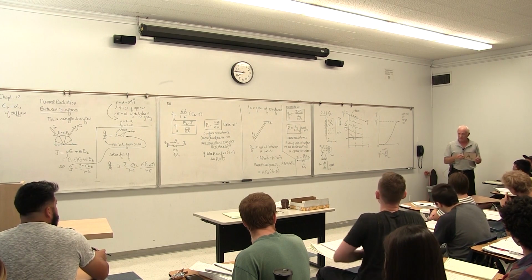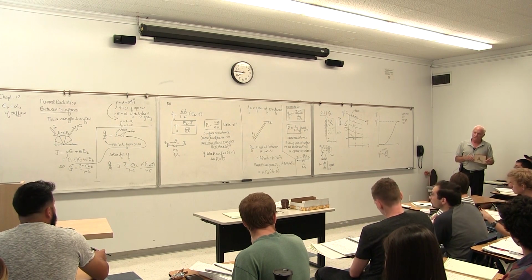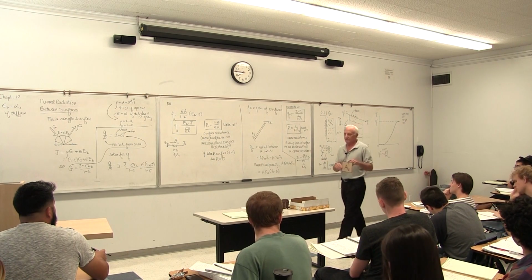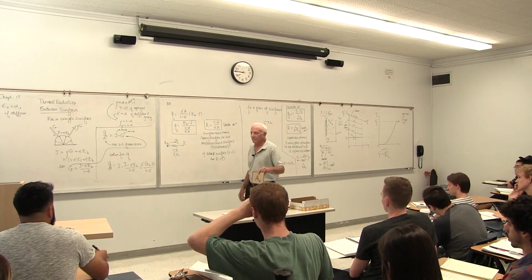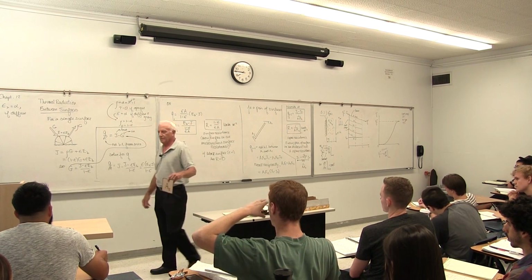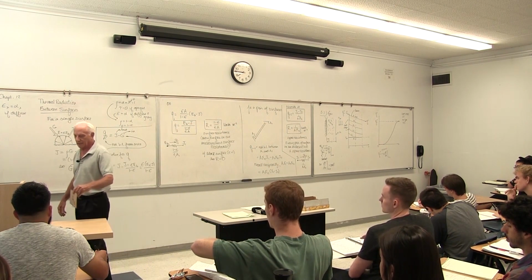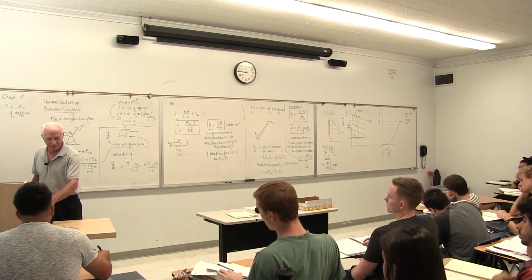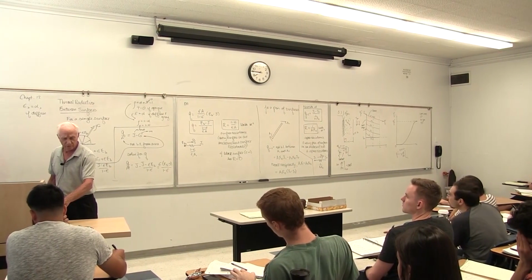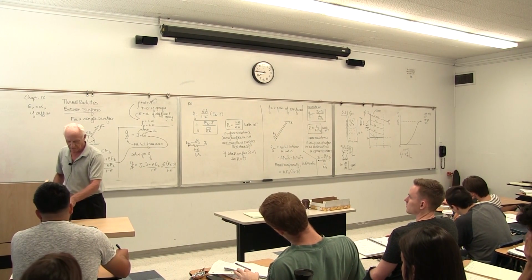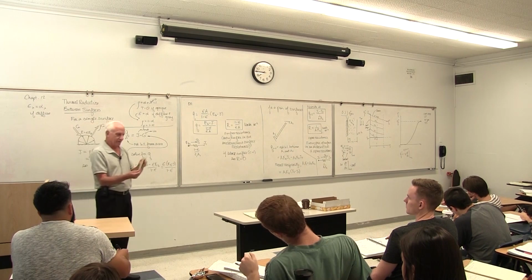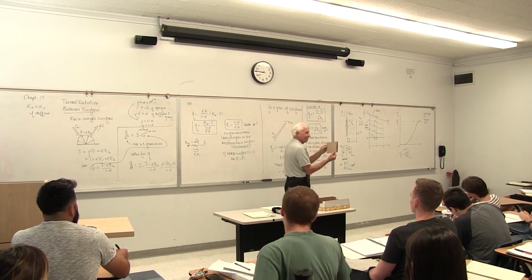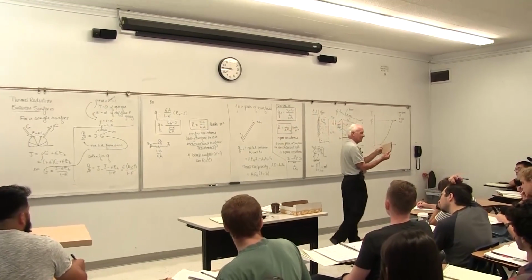So the view factor might be 0.05. Now it's 0.1, 0.2, 0.3, 0.4, 0.5, 0.6, 0.7, 0.8, 0.9, 0.99, because area A1 almost sees all of area A2. The view factor is close to 1. Get them within 1/10,000th of an inch, view factor 0.999. It depends how close they are.